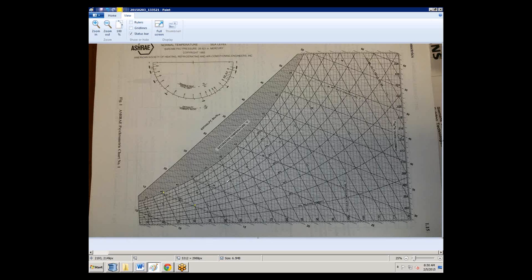So we're interested in that region where our wet bulb temperature would give us the desired chilled water temperature when we look at what the approach of the towers may be. So if I put a couple of yellow dots on here, if it was 50 degrees outside and 40% relative humidity, you've got a 40-degree wet bulb with a 3-degree tower approach, say, or even 5-degree tower approach.